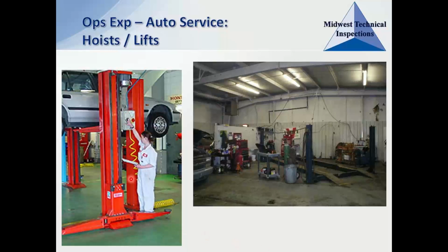Like on this hoist over here, we have the main column that's lifting it up, but then we have a safety column over here. It's got a kind of latch system or a ratchet system. As it goes up, it's got a little lever that, as it goes past each point, flips up, and so it's got that fail safe. So if it falls, it's only going to fall that far. It gives it that security and protection.